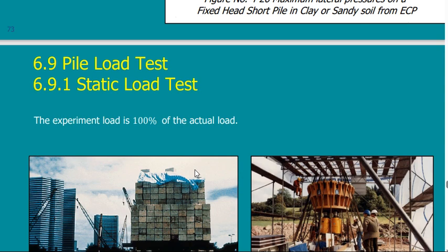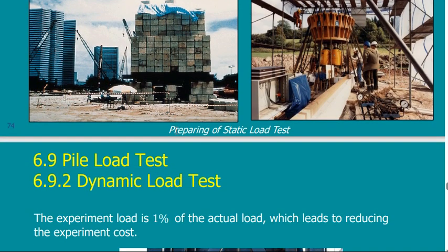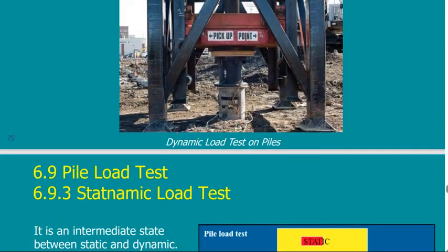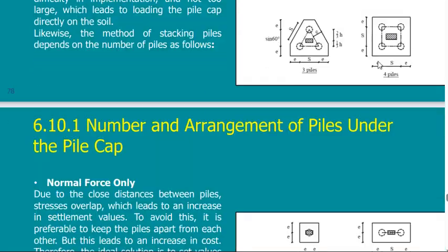You will find that each one gave a different value. So which one to use? Use any one, but at the end, do a verification for this load by a pile load test. So pile load test is very important. Just read this. This is normal.